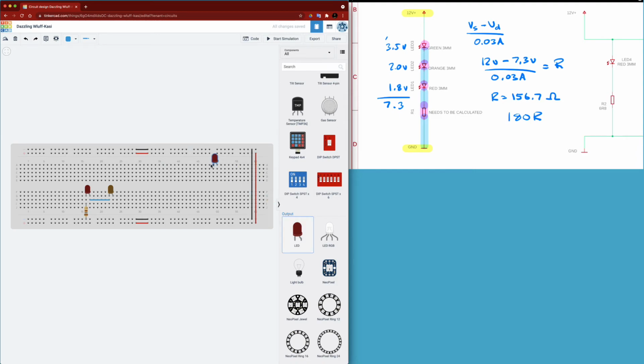So I need to go grab one more LED, and again first I'll switch that to green, and then I'll grab a blue wire again, connect the positive leg to the negative leg, and essentially what we have on the breadboard is exactly the same as what we have on the schematic drawing.